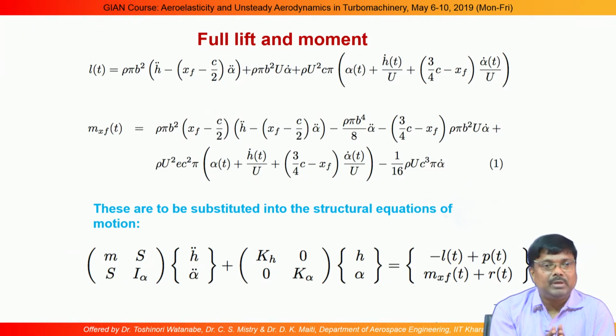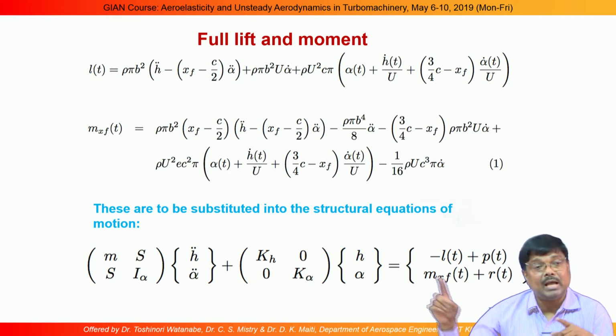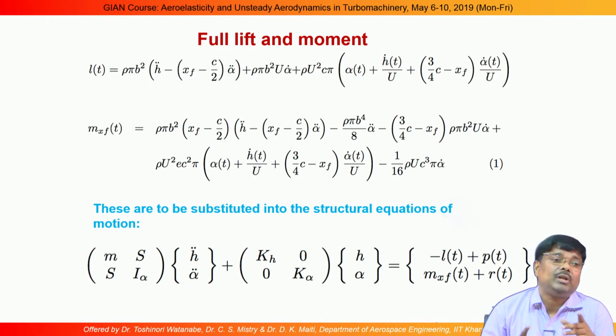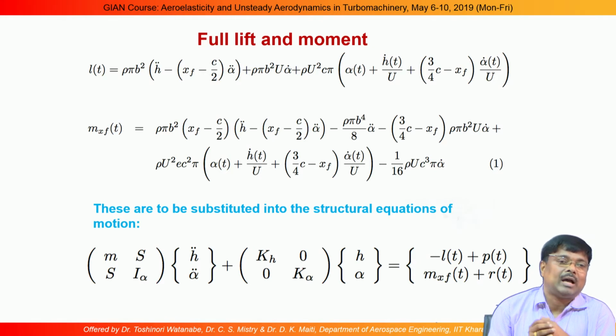There is a possibility when effective damping becomes 0, that we call flutter. When effective stiffness becomes 0, it becomes divergence. So, in the dynamic equation, if I do the flutter analysis for a very high velocity, beyond a certain speed, I can identify divergence also.